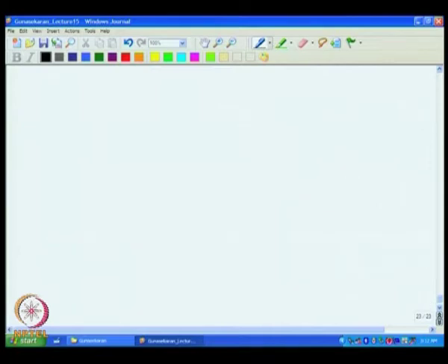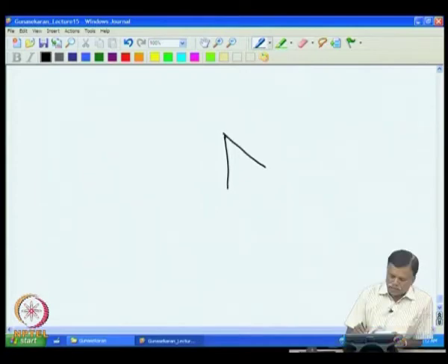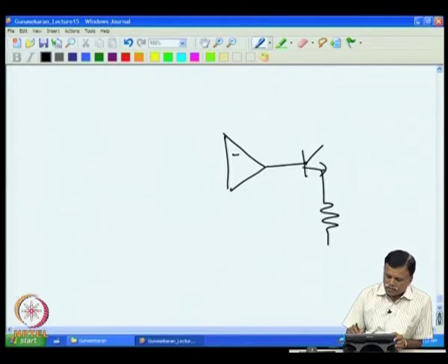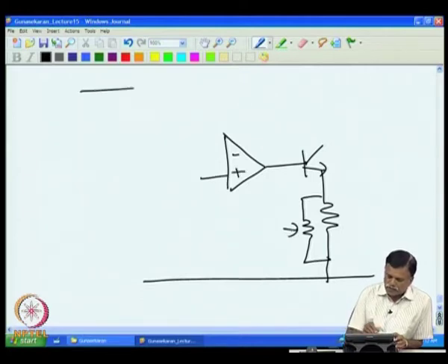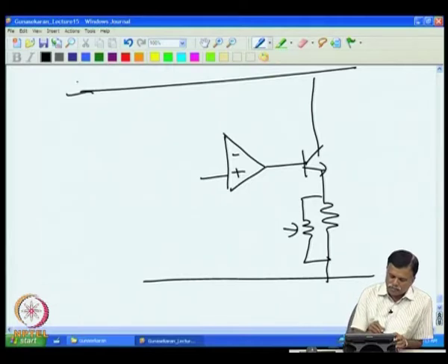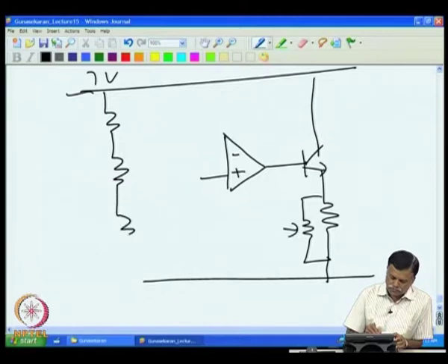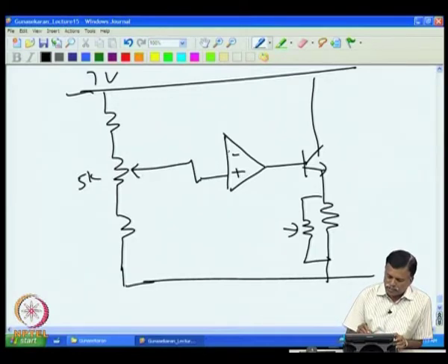So, we now look at the current converter stage to compute the errors. First we pick up the simple circuit here. The current converter looks like this, and the span part here, and this is the regulated voltage 7 volt which I had set. Then we had various resistors, this is that 5K. Then this is given to the reference zener.